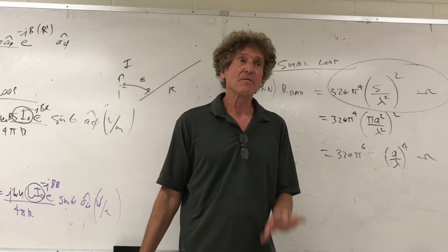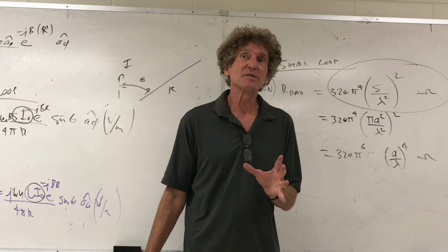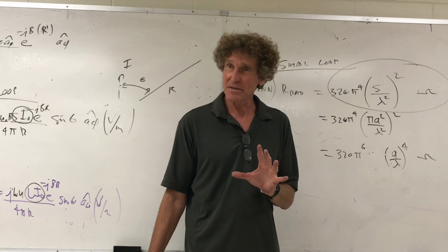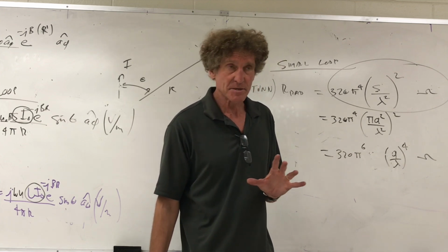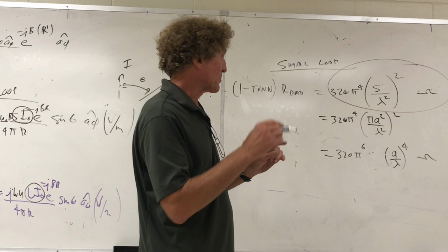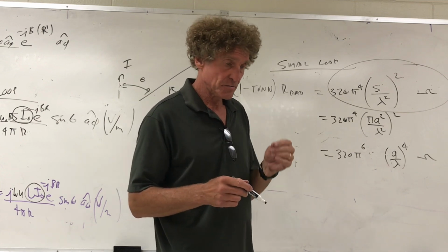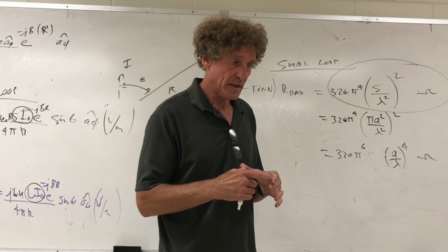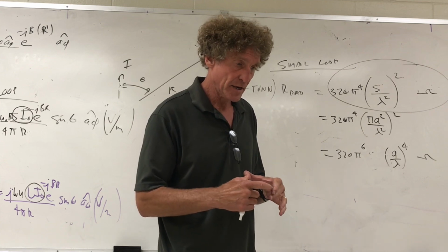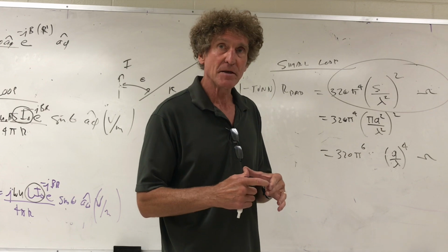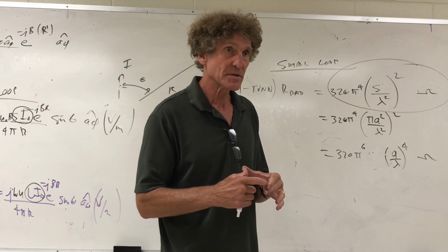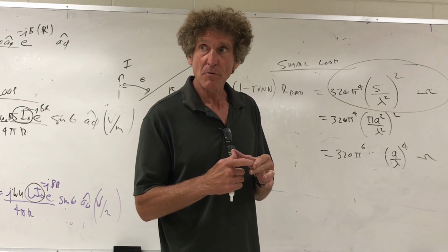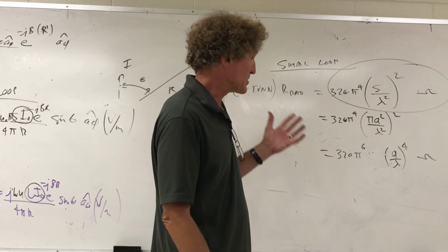You're going to find out it's about the same impedance as a short dipole of similar length. As a matter of fact, I haven't done this one, but if you put the perimeter of an actual loop antenna equal to lambda over 10, and you compare that to the impedance of a short dipole, I think you're going to see they're almost on top of each other, but I haven't done that one in a while. You all with me? So it's very low is what I'm getting at.